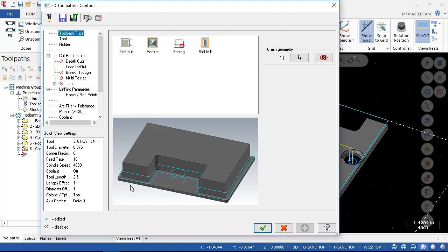When you're thinking absolute, I'm telling it to go an absolute minus 0.25 or minus 0.5 inch, and that becomes part of your habit. As you're selecting more wireframe geometry, the incremental gives us those steps, and our value is 0 in relation to the geometry that we picked, to the chain that we picked.